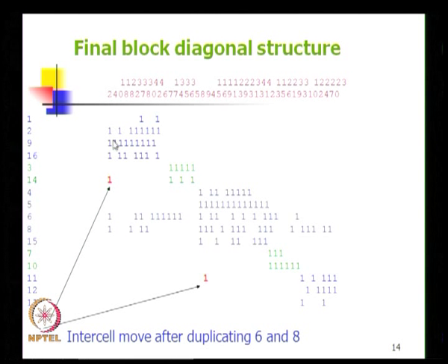The other one is called part subcontracting, or component or operation subcontracting. Can I take this component 2 entirely out of this cell and subcontract it outside, to another person or organization, and get part number 2 as a subcontracted item bought from a subcontractor? Sometimes subcontracting the entire component may be an advantage if it is a standard component or part, but if it is not a standard component or part, then subcontracting would be more expensive.